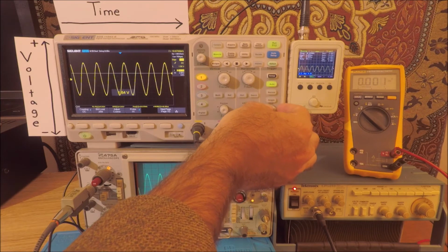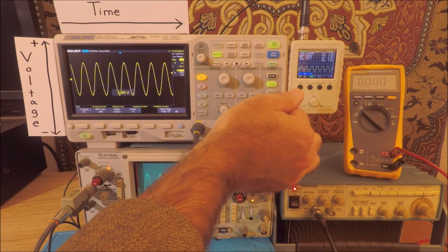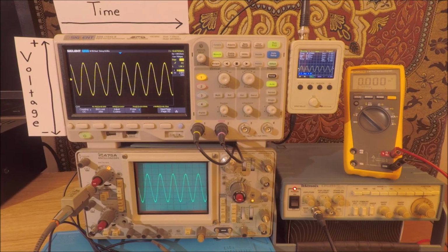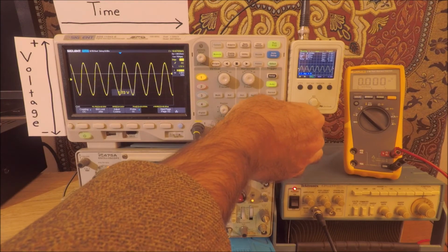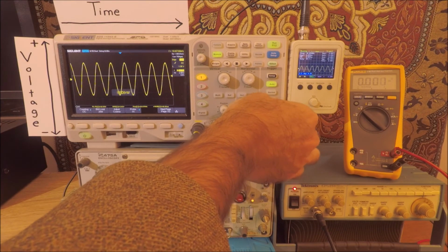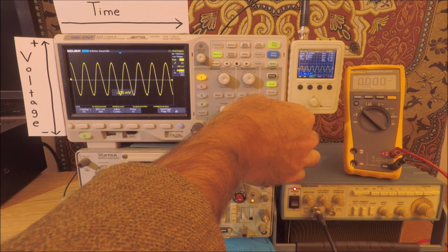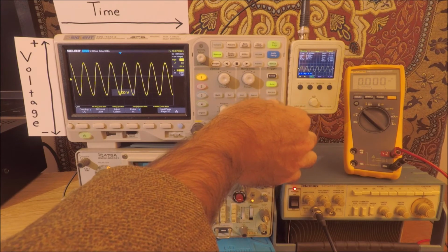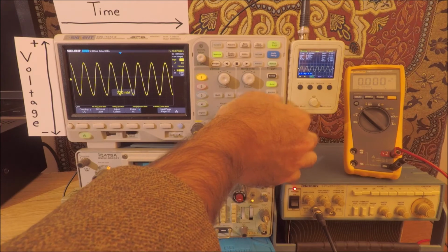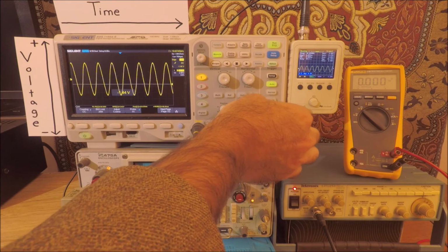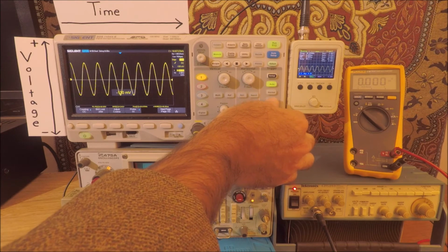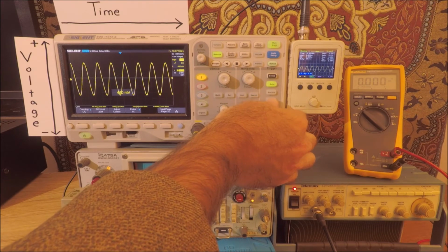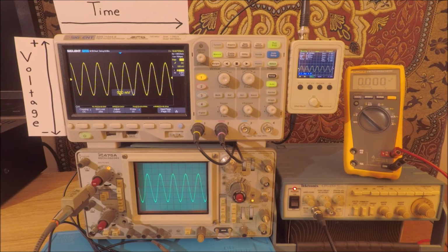What the threshold control here with the trigger knob is doing is it's aligning the crossing of that signal through that horizontal threshold with the y-axis. That's why it's sliding the waveform right and left. As long as I set the trigger threshold within the upper and the lower peaks of my continuous waveform here, then I'll have a nice, stable, repeating waveform that we can lock into time and view.